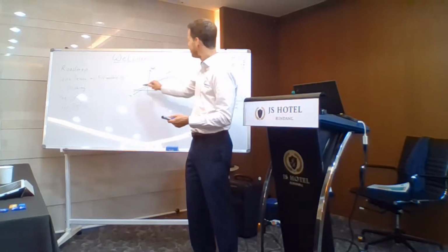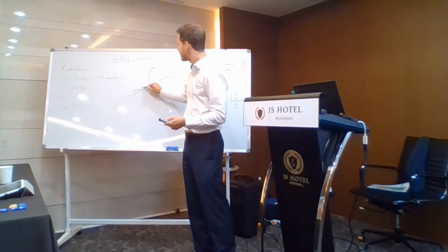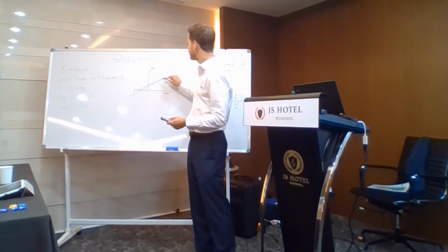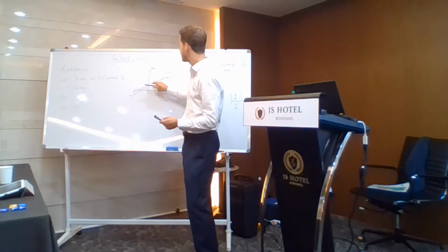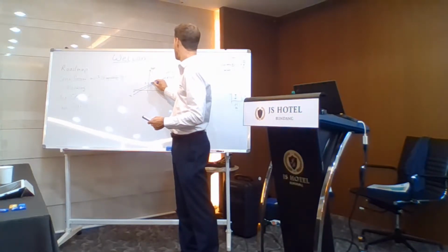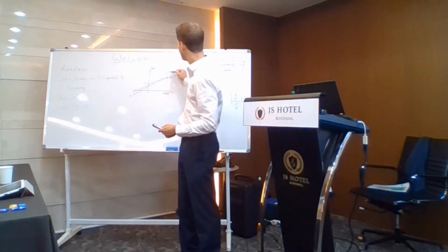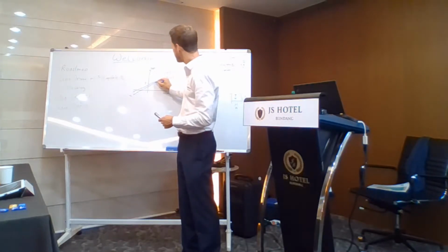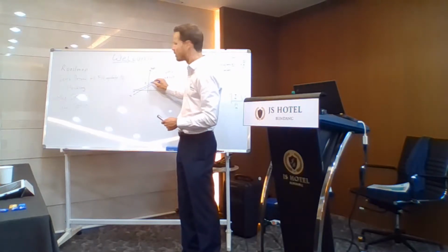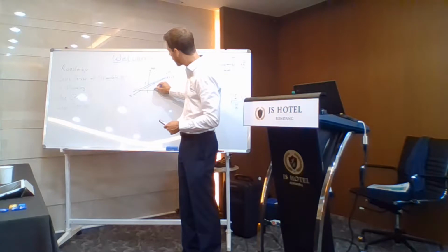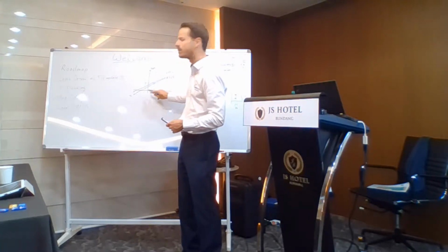So we put both curves into the EEPROM, and now if somebody wants to access, for example, 2 diopters, and the temperature is maybe between 30 and 45, maybe 35 degrees, then the controller will calculate, based on these points of the calibration data, what kind of current do I have to output.